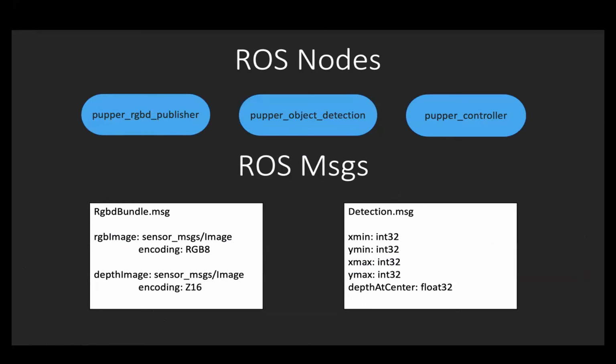So yeah, originally we were using the Intel RealSense ROS packages to publish RGB data, but for some reason it didn't like some of the configurations I was trying to give it, such as reducing the camera resolution and increasing frame rate. So I ended up just developing my own ROS node that drove the RealSense camera directly, and then published RGB images and depth images to whoever wanted them.